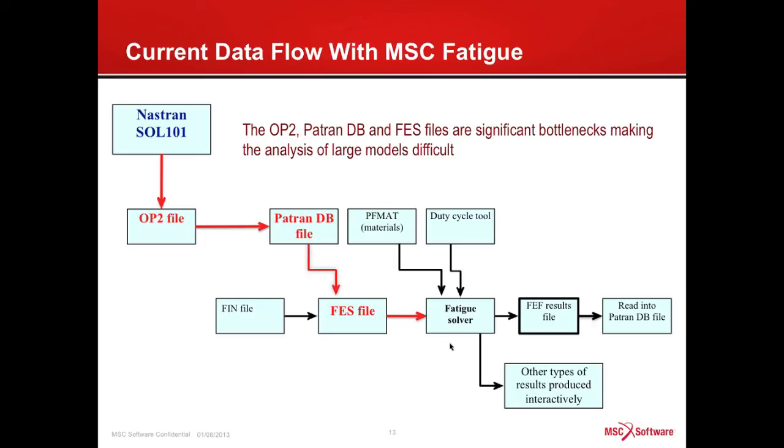So now I talked about the secondary process for fatigue. MSC Fatigue actually works within Patran. So you might even call MSC Fatigue Patran Fatigue. You start Patran up, and the first thing you have to do then is read the OP2 file, read the stresses into your new environment. Now I'm giving the example of Patran, but really the following comments apply equally to all commercial solvers. Whichever commercial solver is being used, there must be a mechanism to read in those stresses.